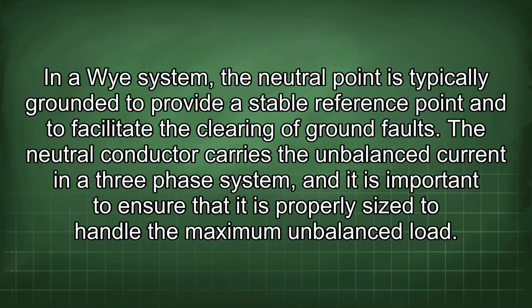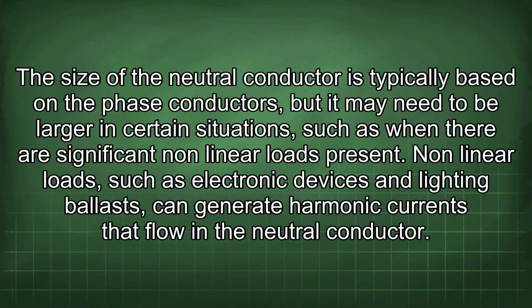In a Y system, the neutral point is typically grounded to provide a stable reference point and to facilitate the clearing of ground faults. The neutral conductor carries the unbalanced current in a three-phase system, and it is important to ensure that it is properly sized to handle the maximum unbalanced load. The size of the neutral conductor is typically based on the phase conductors, but it may need to be larger in certain situations, such as when there are significant nonlinear loads present.